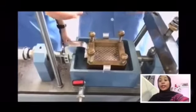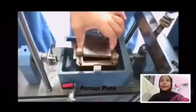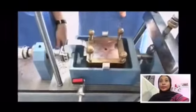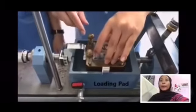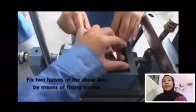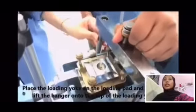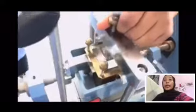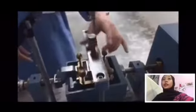After the perforated plate, we put the porous plate. After the porous plate, we put the loading plate. Fix to half of the shear box by means of the fixing screw. Place the loading yoke on the loading pad and carefully lift the hanger onto the top of the loading yoke.